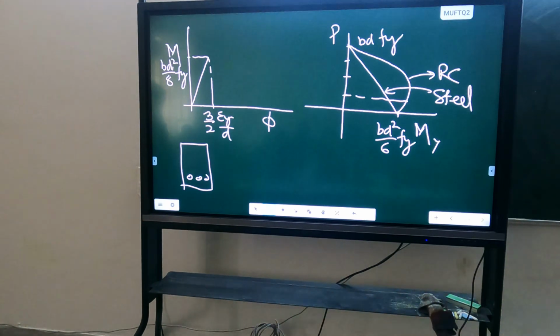Sir, I think in case of steel, the cross-section area is uniform throughout, and in case of RCC, below the neutral axis we take it as cracked, and we are concerned only with the steel area. Also, in steel, the modulus of elasticity in tension and compression is equal. In concrete, the modulus is equal, but the strength is different.